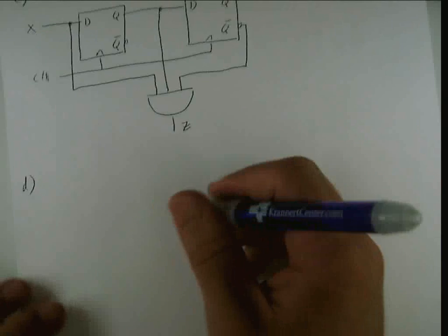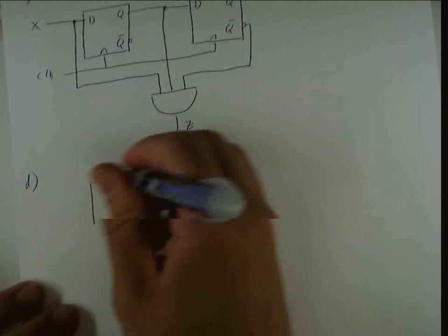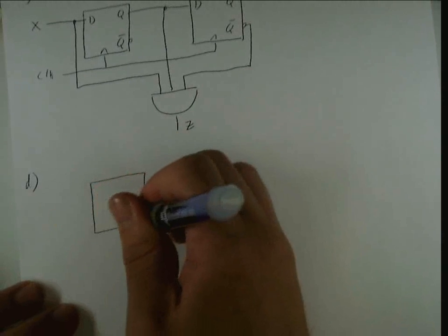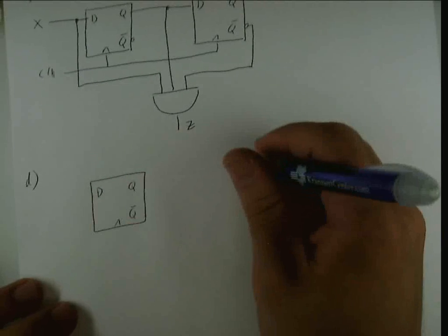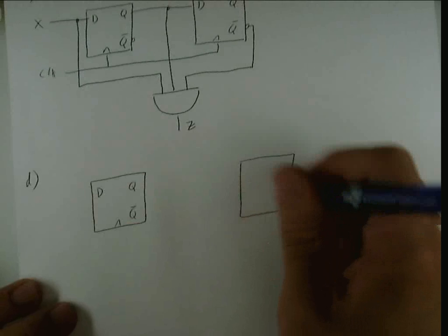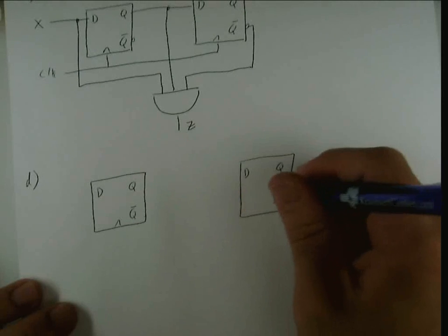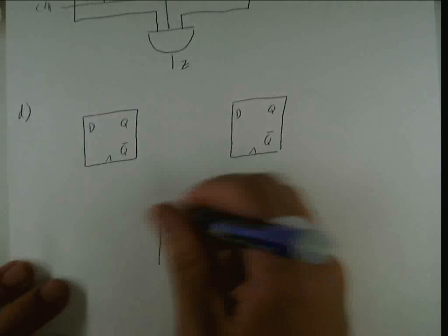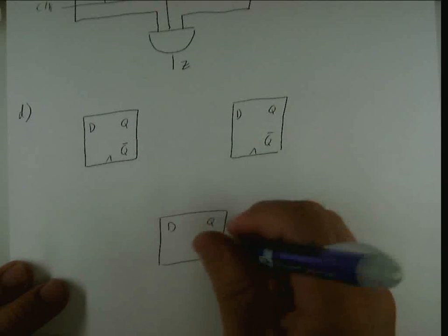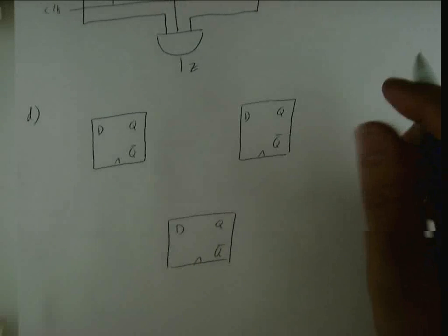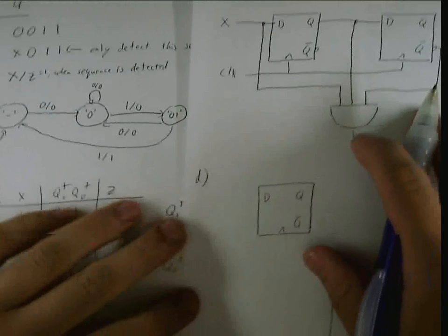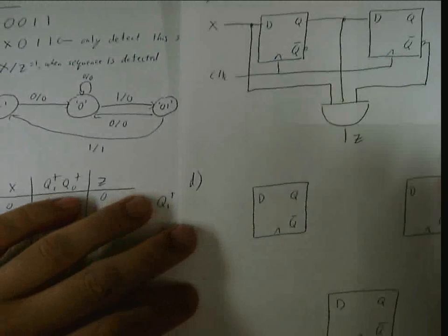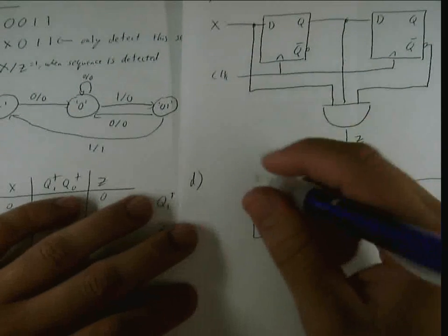And then finally we've got implement your state diagram using one hot design. And so since I have 3 states, I'm going to need 3 D flip-flops. So we need D, Q, Q bar. D, Q, Q bar. And D, Q, Q bar. And I'm going to do this the way I prefer to do it, which is actually writing out the expressions rather than using the decoders. You can use the decoders and you can use muxes as well. Both are extremely valuable, and I may actually change my mind once I actually start on this.